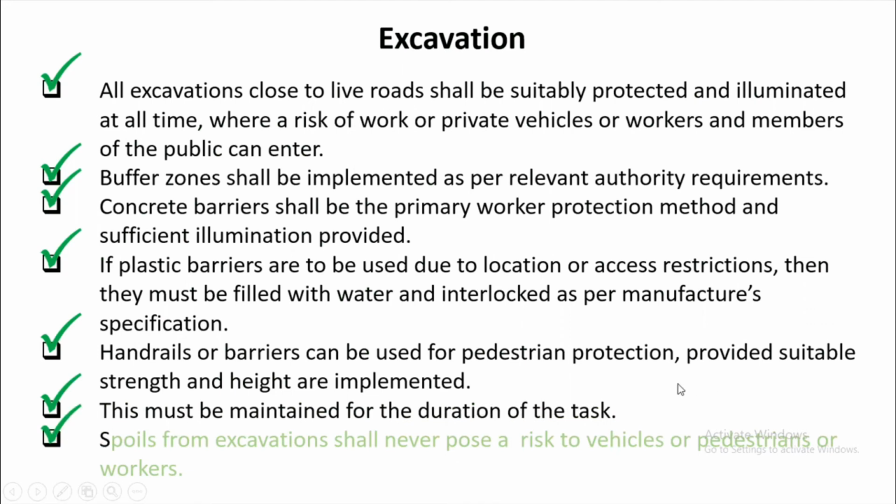Spoils from excavation shall never pose a risk to vehicles, pedestrians, or workers. The issue here with the spoils is that if you place them without barricading them with visible signages and lightings, they will be hit by motorists, and a motor vehicle accident may happen in your work area.